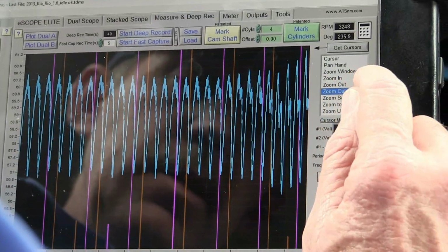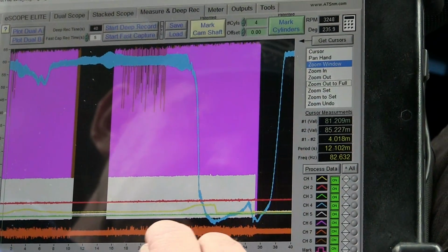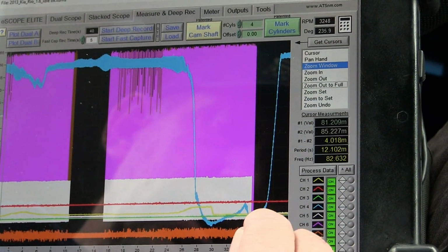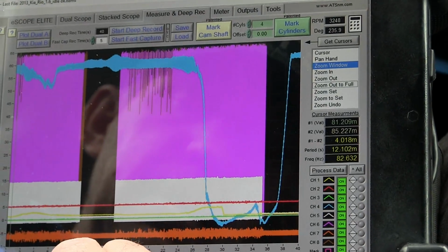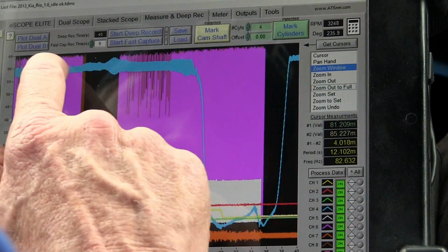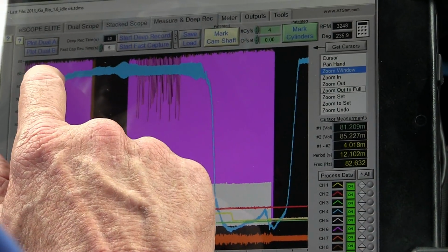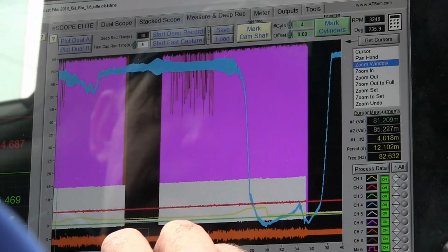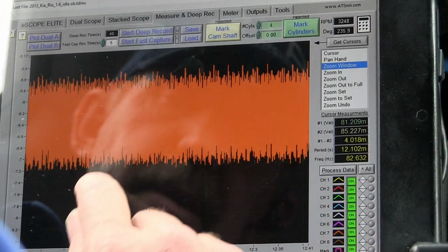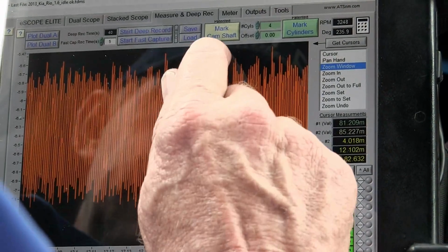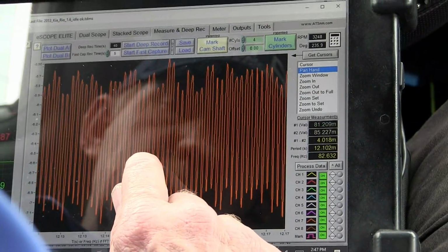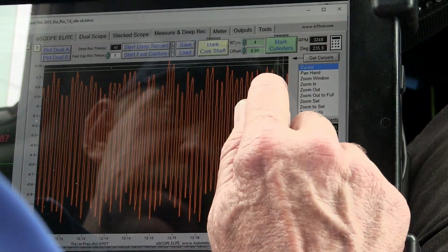Now let's look at the rest of this. What I'm really interested in is down here. This is the amp reading from the pump. So right here I have pressure. We can see that I have about 60 pounds right there. So let's come in and look at the pump speed. What we're going to look for real quick is sort of a signature.